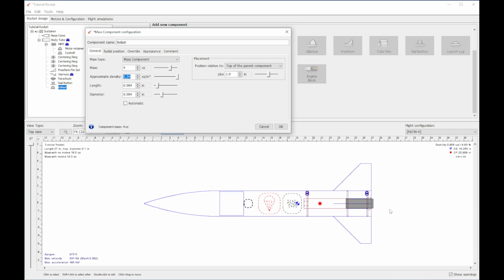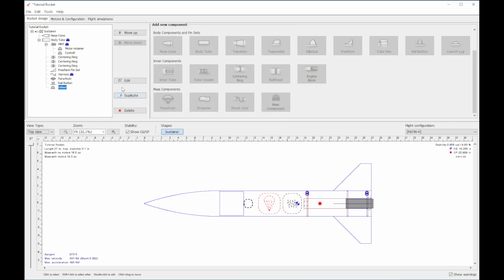It would be another video to show how you can model that base drag in OpenRocket. You add a component off the end here that's sort of a massless conical shape, and it adds that base drag factor into the stability calculation. So even though this is really your caliber of stability, whether that is stable or not is figured out using that trick. So I'm not going to do that right now. And even though the caliber is less than 1, I think it's still going to give me good simulation data. So I'm just going to leave this ballast at 4 ounces. That should be just fine.